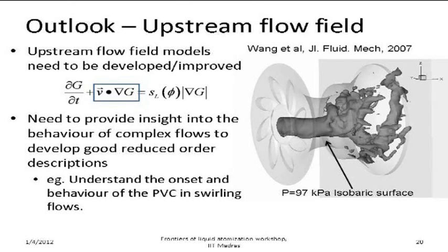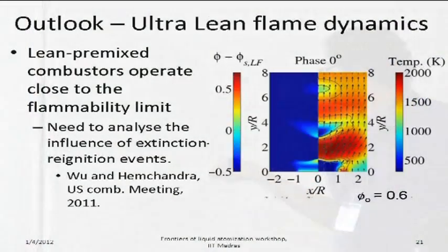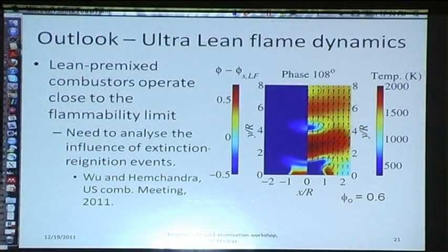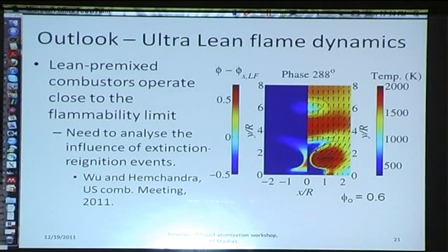And finally, I did the whole thing for this level set method. Everything works when you have an unbroken flame. So the results that I showed you were for a nominal mean equivalence ratio of 0.85. But what if you go towards low NOx operation, where you have a mean equivalence ratio of 0.6 maybe, or even lower, 0.52, 0.53? In such a case, this is a result that I presented at Atlanta earlier this year, and this is essentially a slot flame, which is again forced with a mean equivalence ratio of 0.6, with an amplitude that is about 60% of the mean.